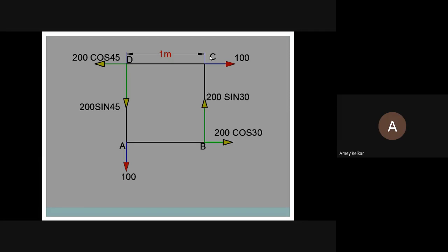First, note down and remember this important point: if the line of action of a force passes through the point under consideration, there will be no moment. That means if the line of action of any force passes through point A, that force will not cause any rotational action, because the definition of moment is force times perpendicular distance. Is that clear? So Akshata, can you tell me which forces will not cause rotation at A?